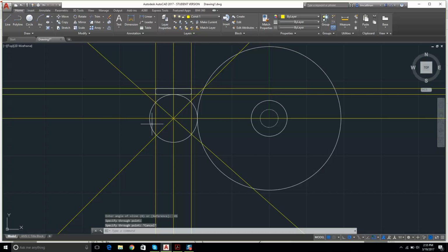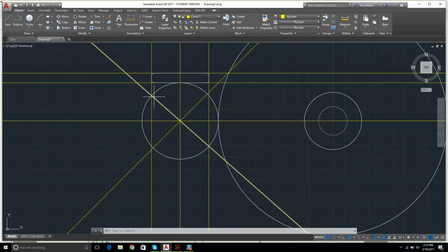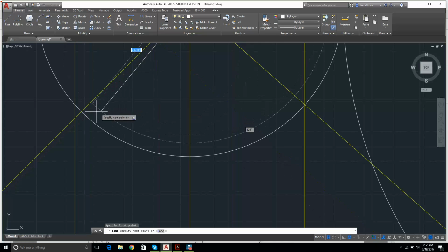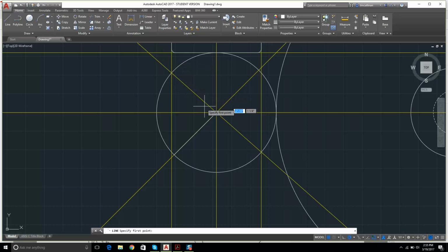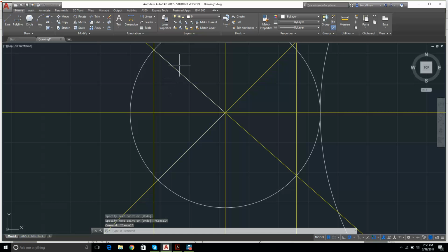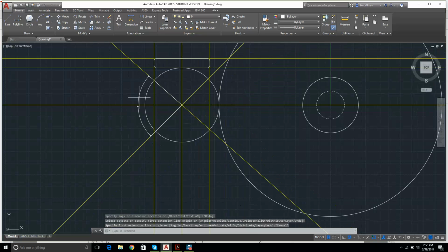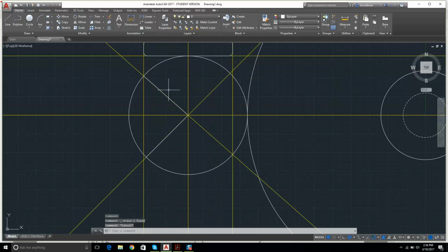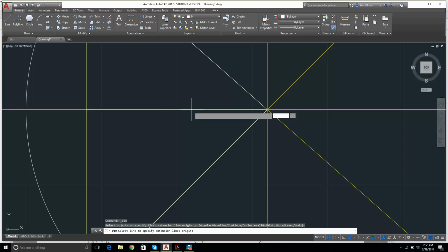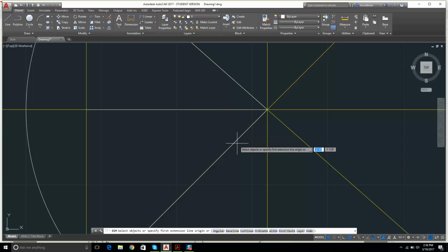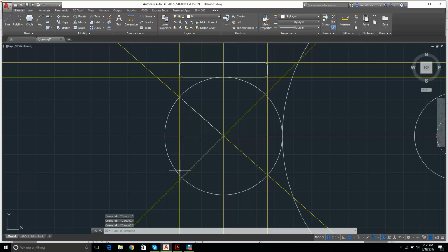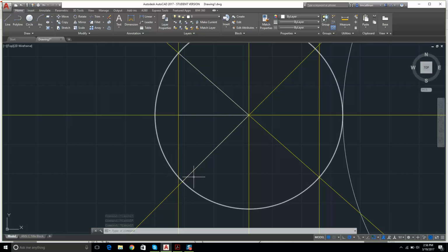Right, now if I put a dimension on here, let's just draw a line. Something doesn't look quite right there. If I draw a line there, and I draw a line there, I should get 90 degrees between those two. From there to there, and I'm getting 86 degrees. Something's not right there. Alright, let's find out which one it is. So we just put this line in, and I'll get a dimension between here and here. That's 41. And then from there to there is 45. I was wondering why these two lines aren't lining up here. There's a gap here.